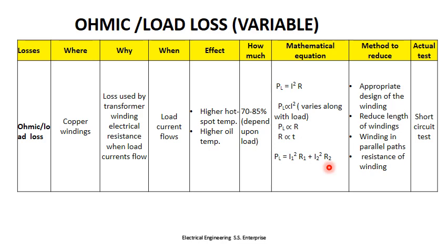How to reduce the ohmic or load loss? By using appropriate design of the winding, reducing the length of the winding and using windings in parallel paths, reducing the resistance of the winding. By using the short circuit test, we can measure load losses.